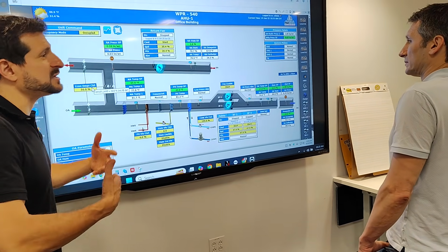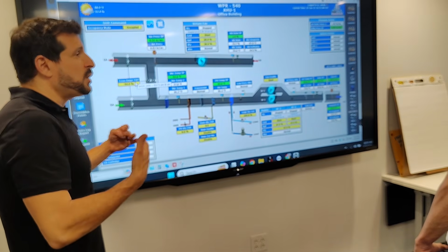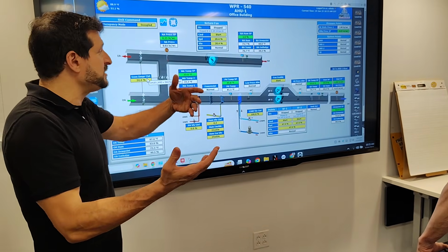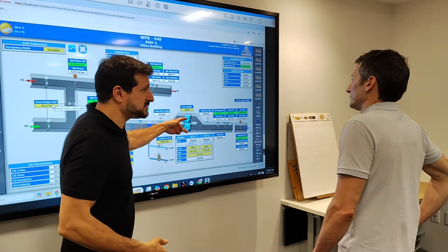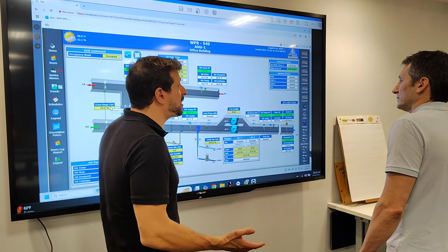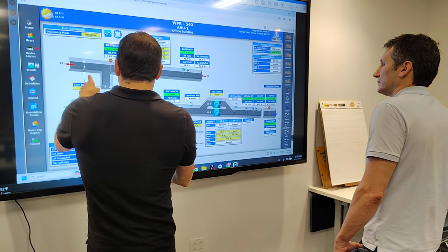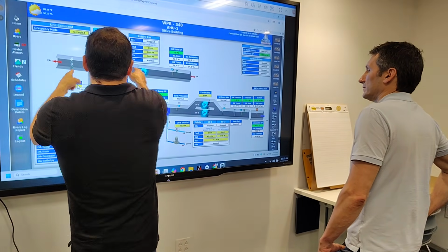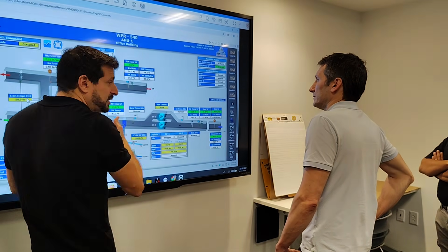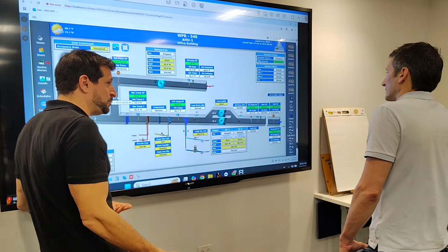So an engineer, when he designs something, he plans it out. Now we have a balance board from 2016, so we have some things that we can do. You design based on the intent, right? The engineer says, I want this to be 120,000 CFM. I want this to be 100,000 CFM, which means this thing always needs 20,000 CFM to come from somewhere else. So at that point, if this thing was 90%, this thing was 10%, this thing was 10%, you still wouldn't have air leaving. You would still have air going like that. If he sized these the same, then you'd have air leaving and coming in, right? So it's all about the initial design and then the initial setup and then that initial balancing.